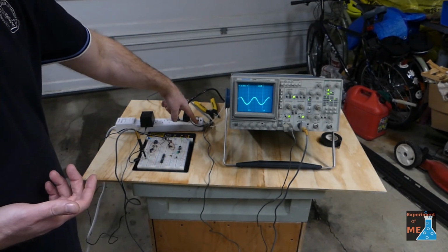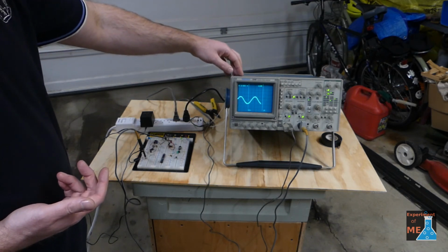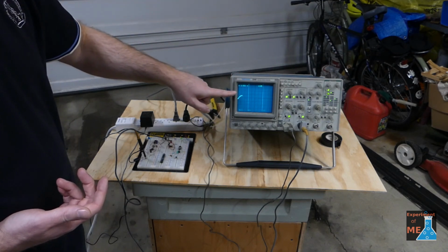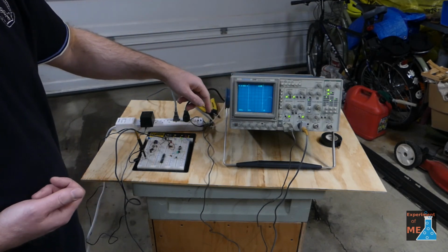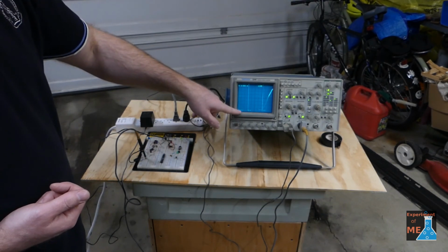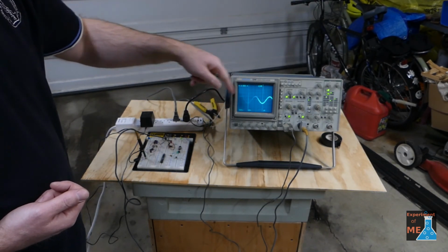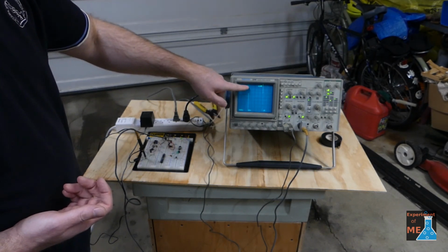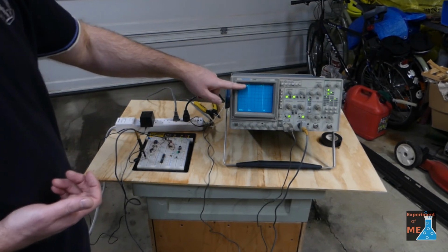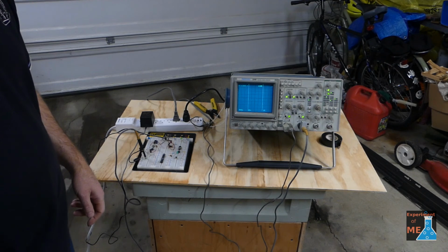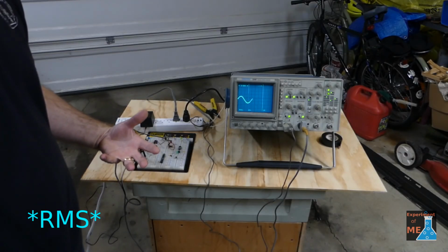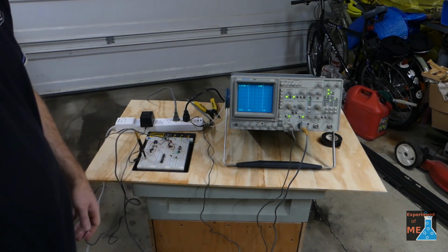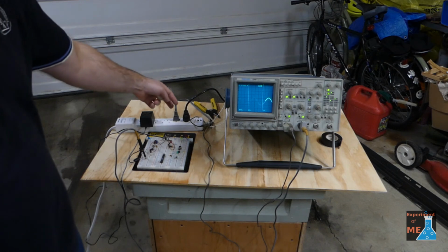And I actually have a second probe here set up to measure the AC voltage, and we can see that that's this much slower waveform here, and I have the voltage division at 50 volts, so we can see that that's measuring, let's see, so if this is our center, about 170 volts peak, positive and negative. And then when you do the RMS calculation, that turns into 120 volts. So that's the 120 AC that we normally get when we plug into an outlet. So that's this right here.